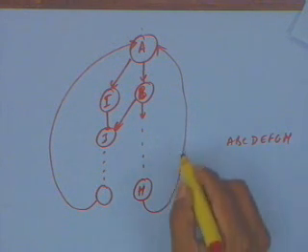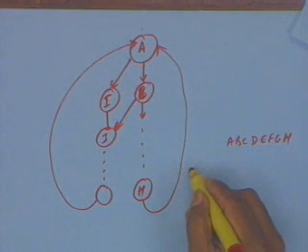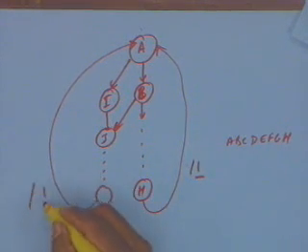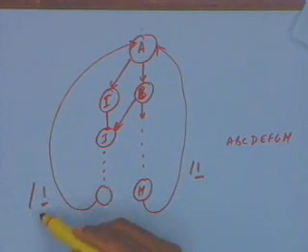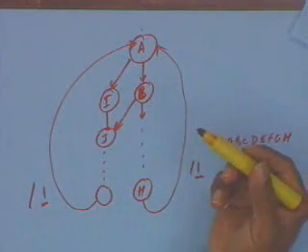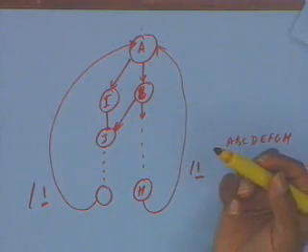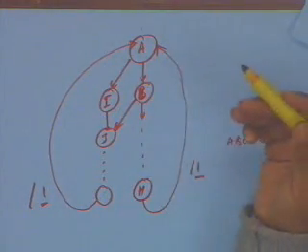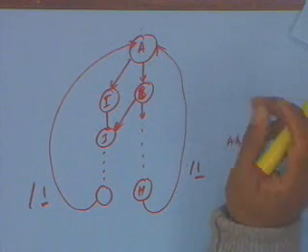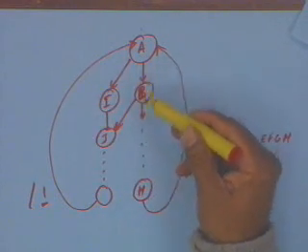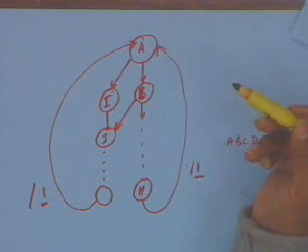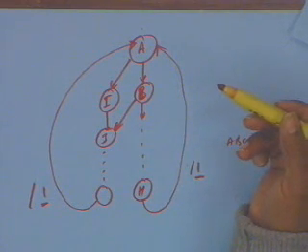To these particular edges I can associate an output, some output 1, which indicates that I have got 8 bits. So I don't need another 8-bit counter for doing that, because this particular state machine itself can give me the first blocking, the 8-bit blocking. If I come back in this particular fashion, then I actually get a correct character.